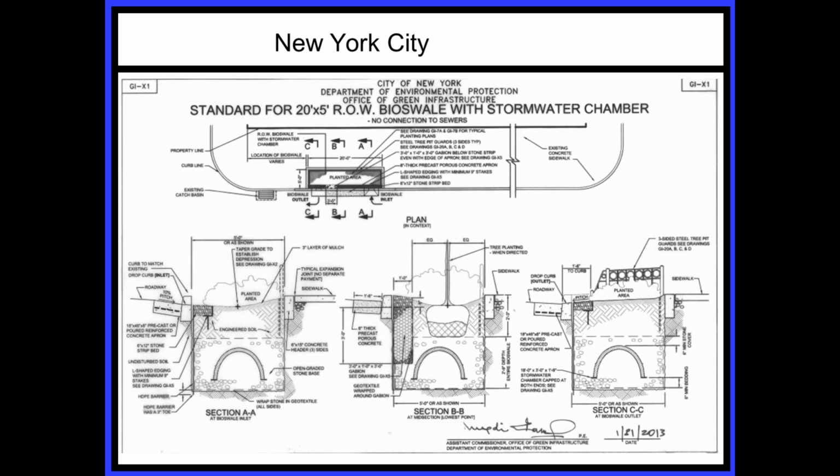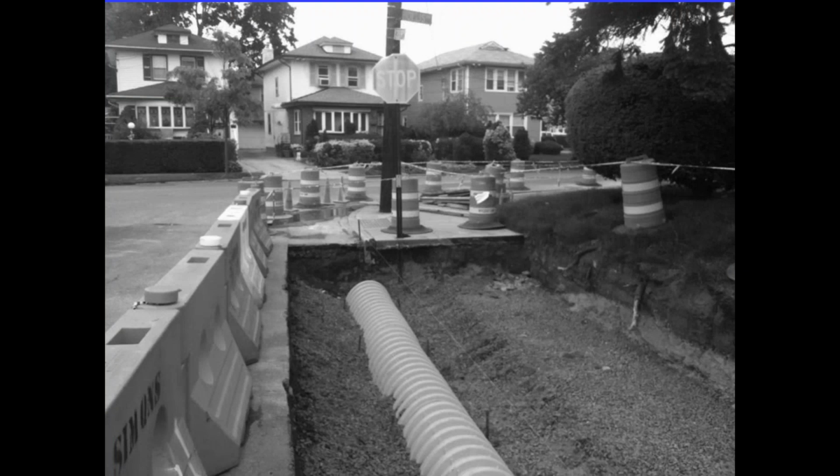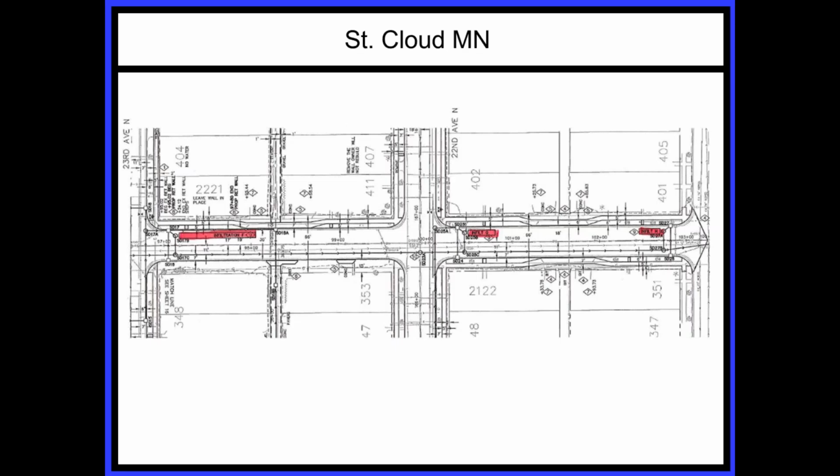So the success of longevity is very low. So they need other methods to store that water, infiltrate that water. This is just an example of how that's being employed out in the New York area. This happens to be a residential, but it could be anywhere. This is a right-of-way example of doing the same thing. I've highlighted in red the 3 infiltration basins.